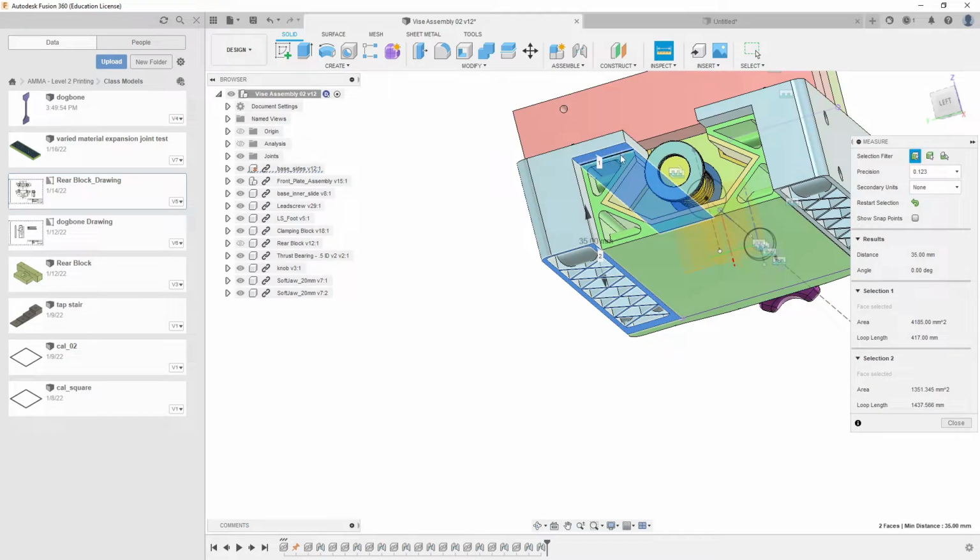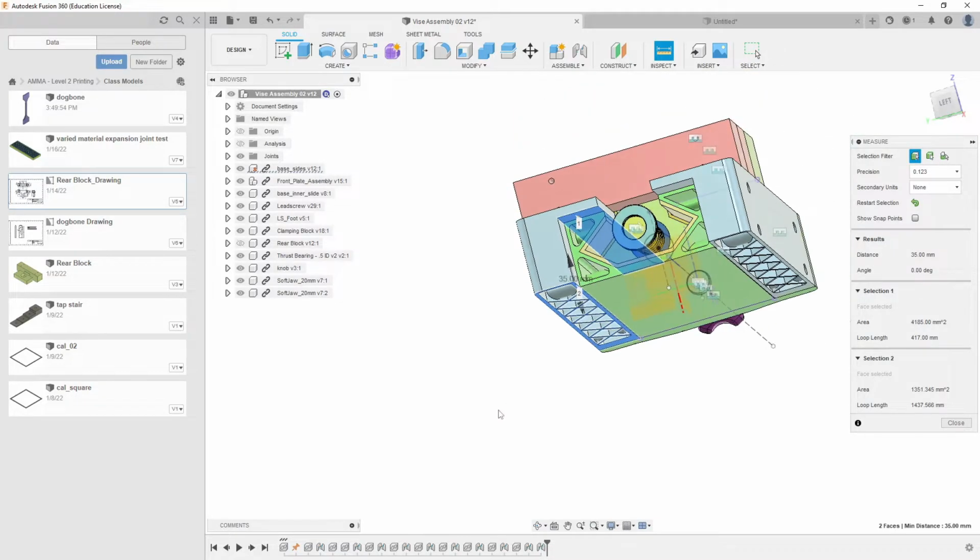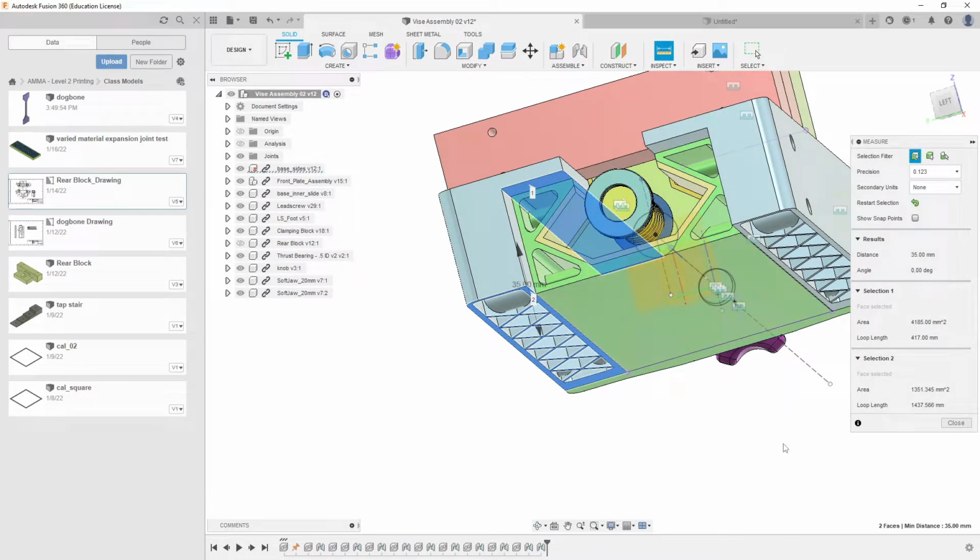If there was any kind of discrepancies up here at the top of the print or the bottom of this blueprint, haha, it would cause this green to not be flush with the bottom here. And does that bother you? If that bothers you, then maybe you'll add, you know, like 0.2 millimeters of some gap tolerance there. So you could think of it this way: would you rather have the blue being down a little bit further or the green being down a little bit further? If I had to make a choice, again, this is going to be a fraction of a millimeter off, but I would like to have the blue touching the table, not kind of teeter-tottering on the green section. So maybe you could add some there, but we'll do that later.